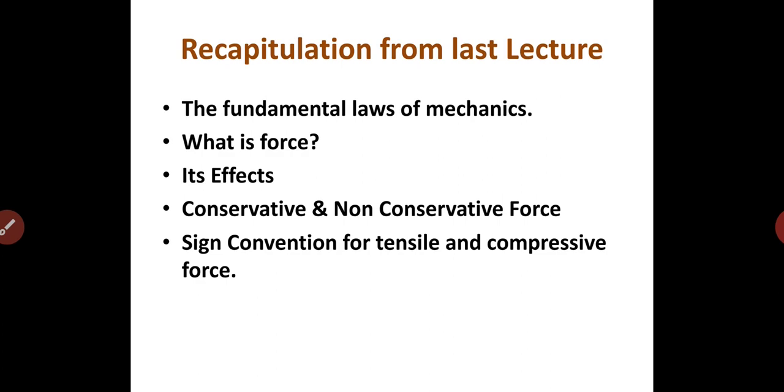You will come to know, when we take the strength of materials part of the subject, that there will be a strain. To counter that strain, there will be internal resistance in the body. That resistance we will be calling total stress. This total stress will be equal to the applied force. But when that total stress is divided by the cross-sectional area, it will be called stress or unit stress. Its unit is Newton per millimeter square. We will go into details when we take that subject.